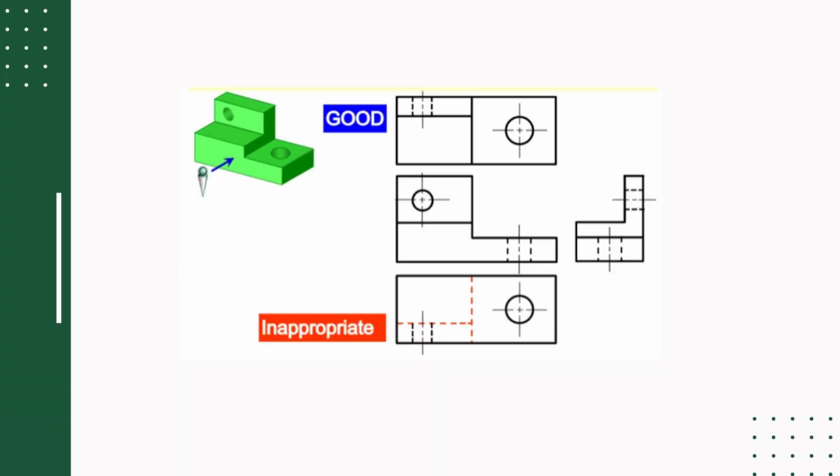Choose the view that has the fewest number of hidden lines. It is not necessary to always draw the 3 views. Sometimes 2 views are enough for the description of the object. Now you can see this dimension, the L shape is shown here. Next, the hole that is shown in the top view. The hole's location can be specified in the same view. It's easy to understand. And below, the one indicated as inappropriate is difficult to interpret. So the first one is good.